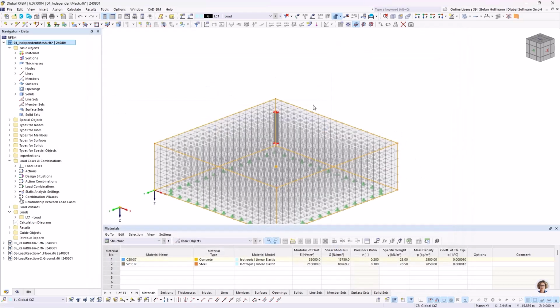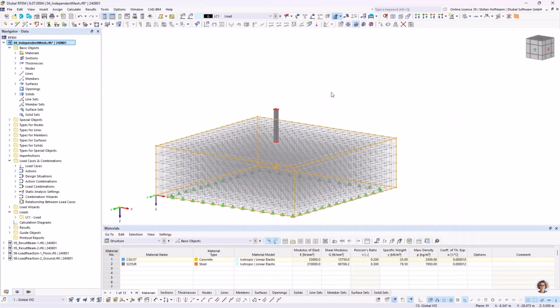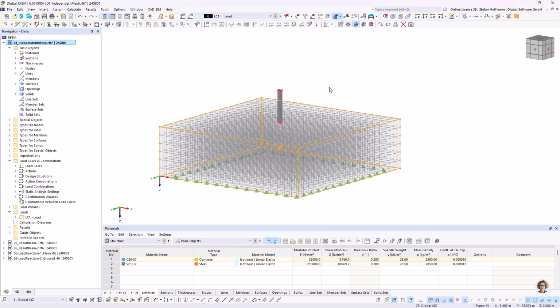These settings will most likely allow you to have a better optimized mesh and shorter calculation times. And of course the forces and the objects will still be connected with some settings in the solver and distribute the forces into the connected objects, but now without the need of the same mesh. Okay, let's go to the next example.